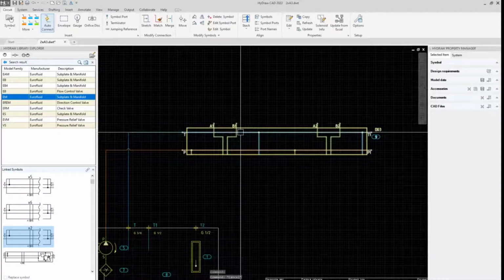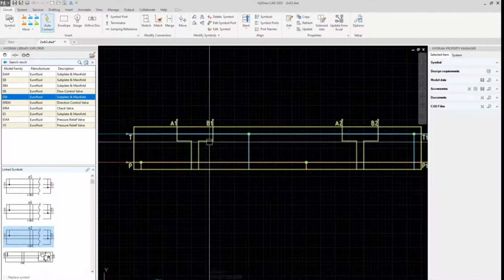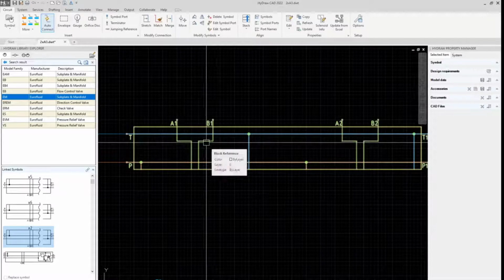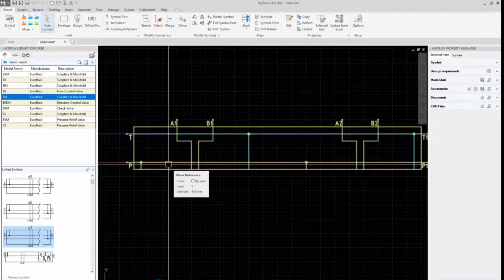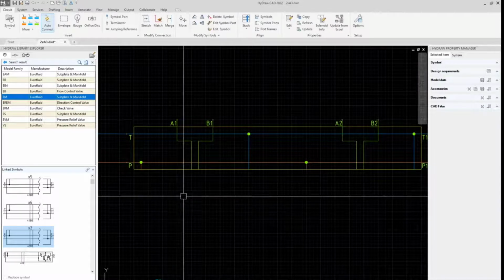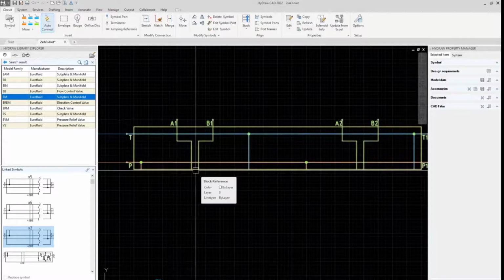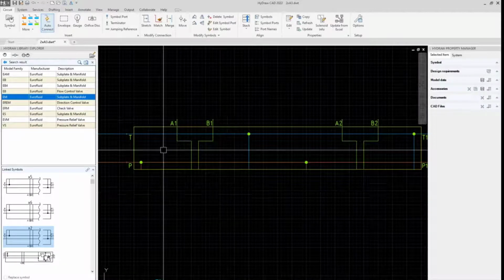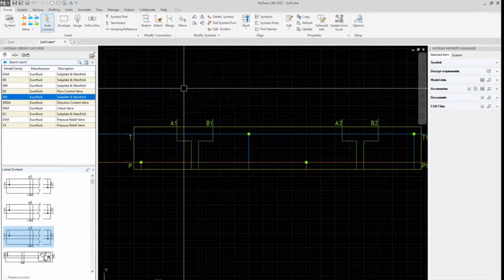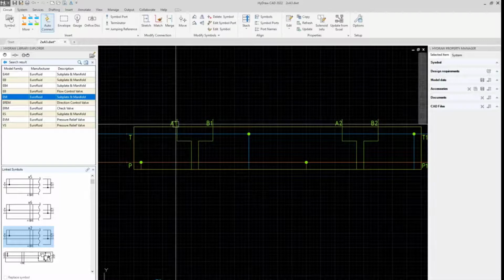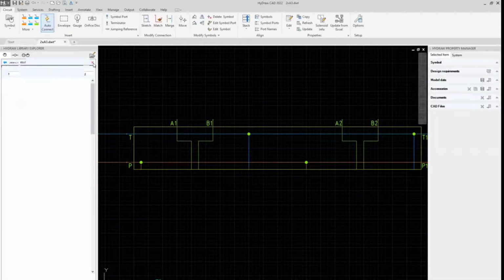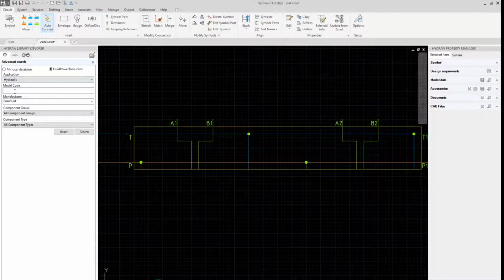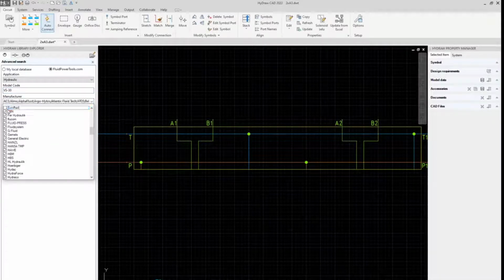The reason for making this symbol so big is that frequently this subplate may have a relief valve, and I see a lot of customers really managing this relief valve as an additional component to the subplate. So they normally in the part list consider the subplate plus the relief valve. So again, there are several techniques. Usually in these Eurofluid subplates, there is a Bosch Rexroth valve called, let me reset, a VS30. That's the model family for a Bosch Rexroth valve.